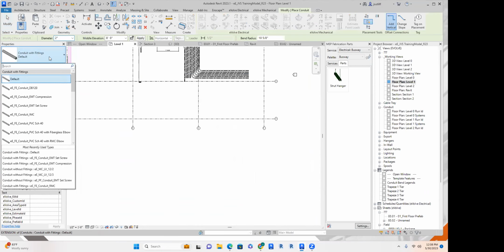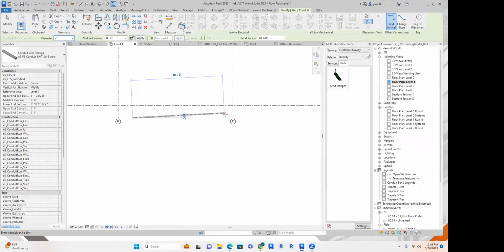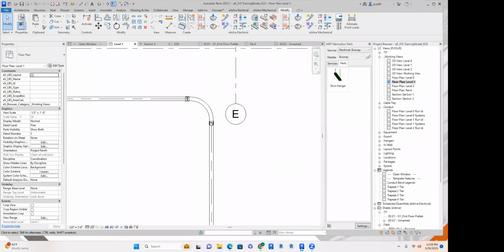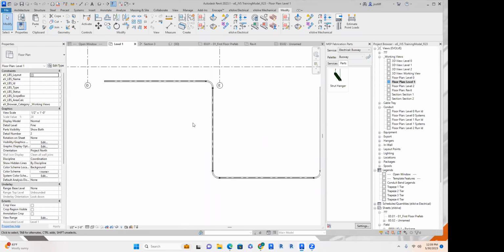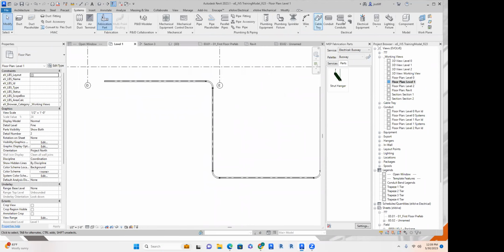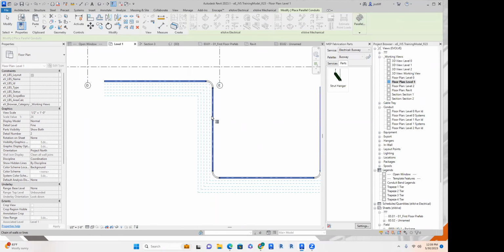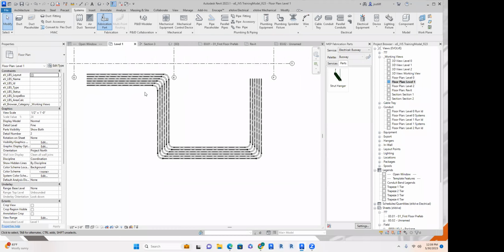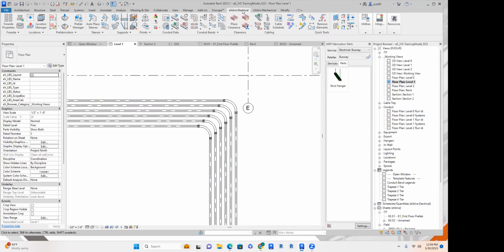So we're going to do our set screw here, and the out-of-the-box Revit or Evolve tools are so great and easy to work with, because as you can see, the elbows already have your couplings and your set screw couplings set in there. We can go through and do our parallel conduit here again. And we're going to keep that at 6 inches because we want to be able to adjust those later.